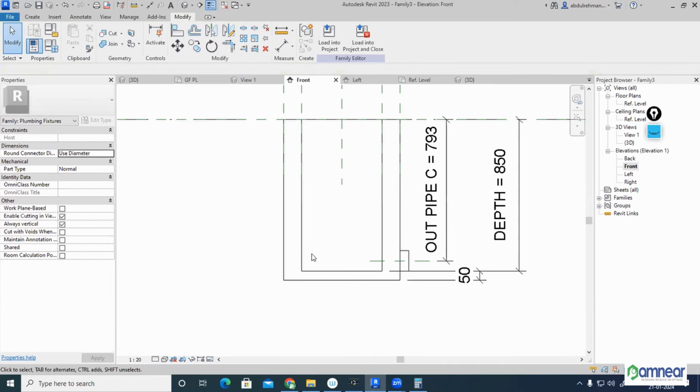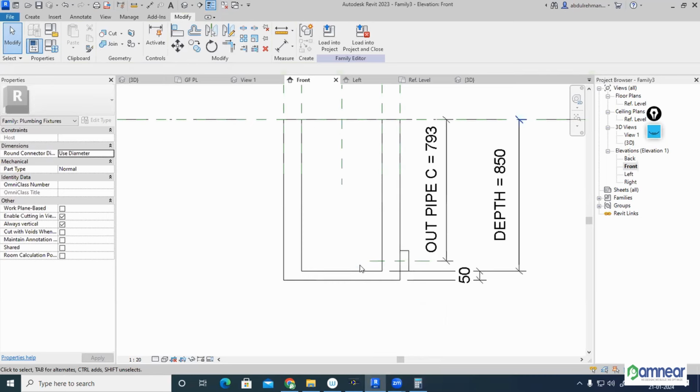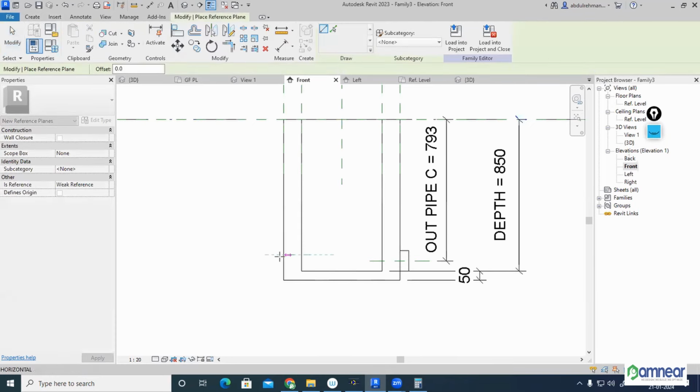Okay. And inlet also I need. Inlet, see this is like a 4-inch 114, no? Now 57.15 we are having from the bottom, plus 25 mm I need from here. So plus 25. So let me select it overall, how much I need. First, I am just creating my reference line. First create it, just go to reference line.